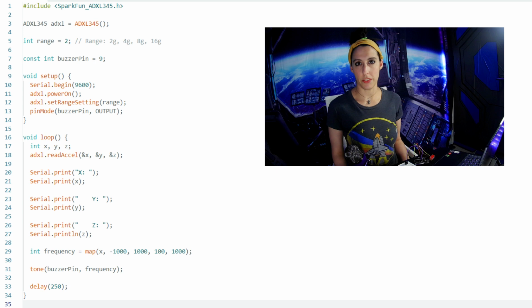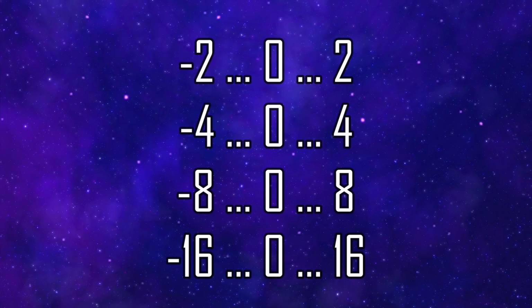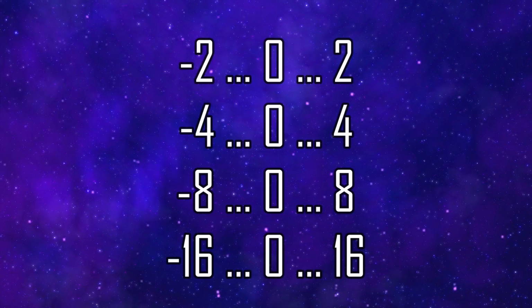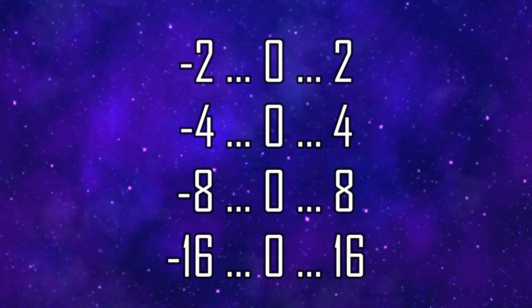When you set the range of an accelerometer, you are setting the minimum and maximum values that it can accurately measure. So setting it to 2G means it can accurately measure accelerations in the range of -2 to +2 along each axis it measures. Choosing a range depends on the expected magnitude of the accelerations you're expecting to measure. Higher values provide a wider measurement range, and lower values provide greater sensitivity. The accepted values are 2, 4, 8, or 16.